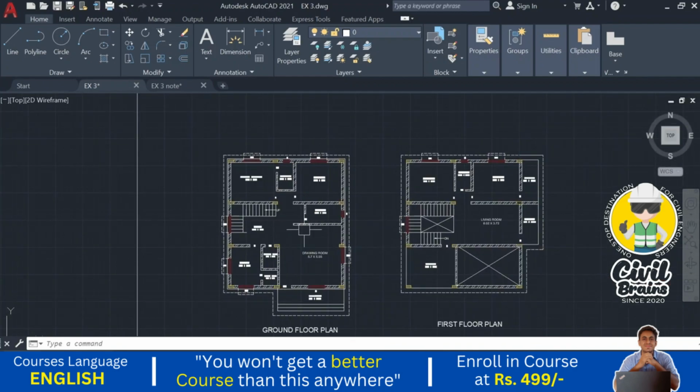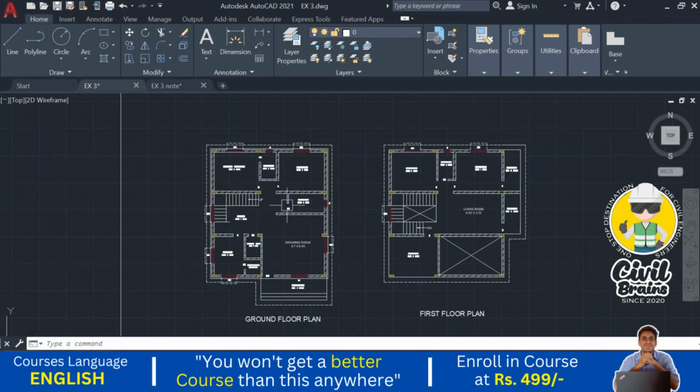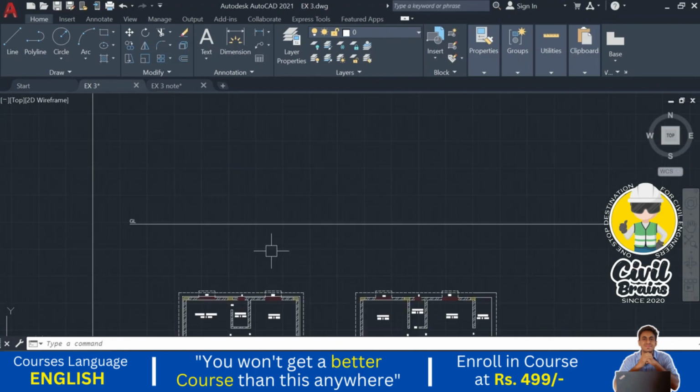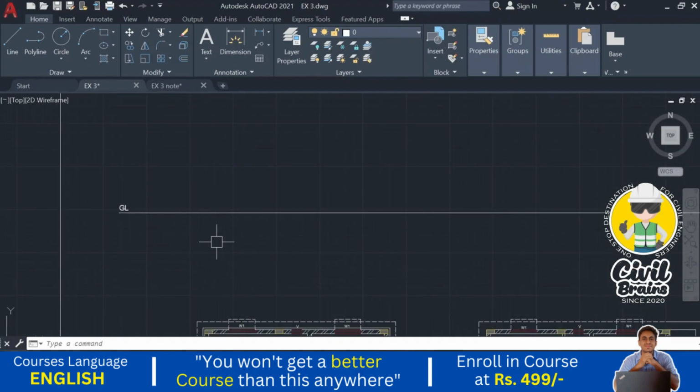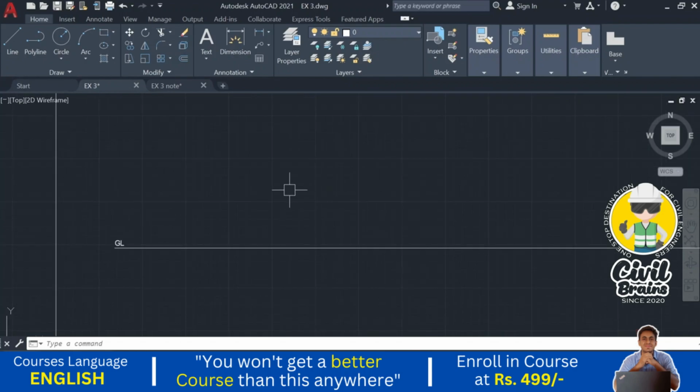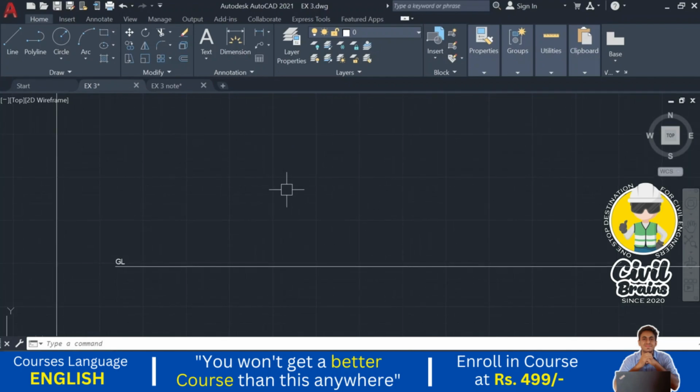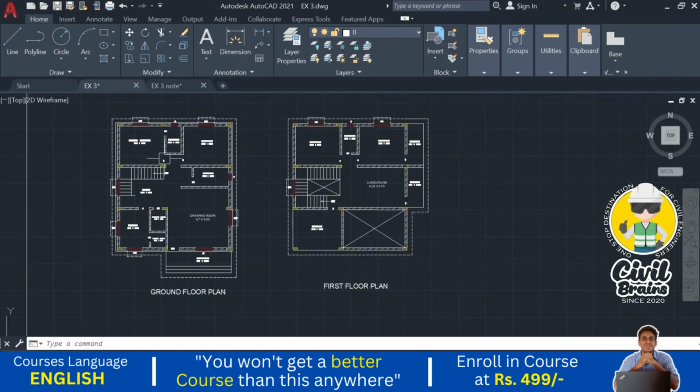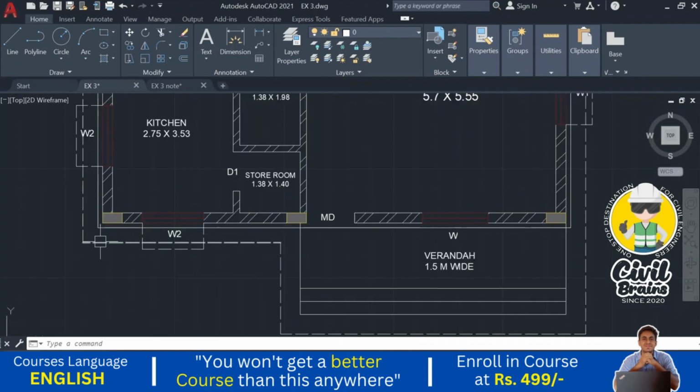So what is next? What is the execution procedure? The first step is excavation. After the excavation, PCC. After the PCC, the foundation. After the foundation reaches the ground level, the next step is we need to provide the plinth. Above the plinth there is the superstructure, and above the superstructure there is a slab or roof, and above the roof you can go with the parapet. Okay, here we are considering the frame structure.